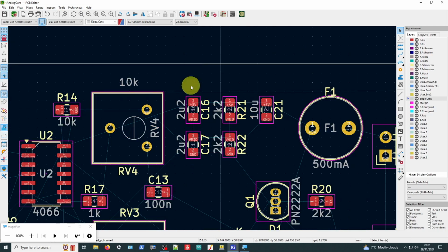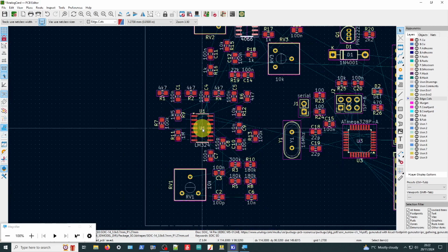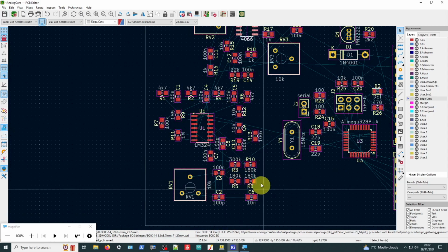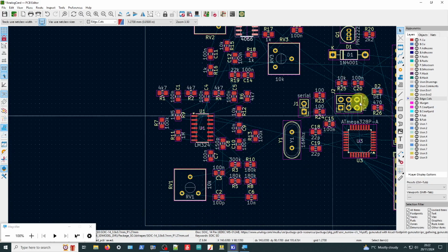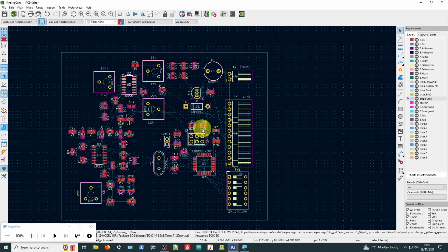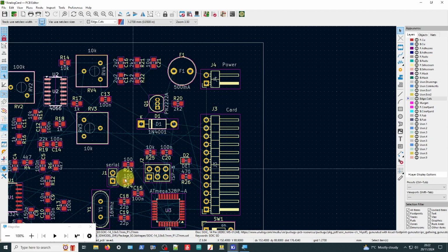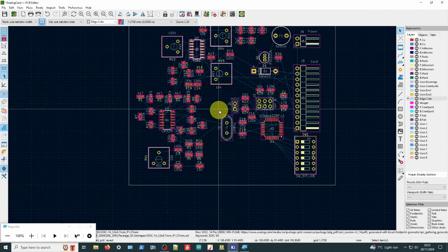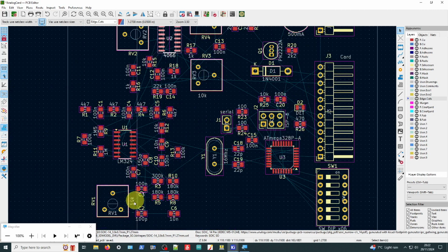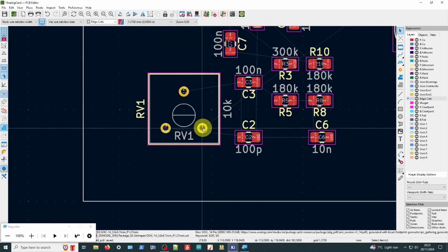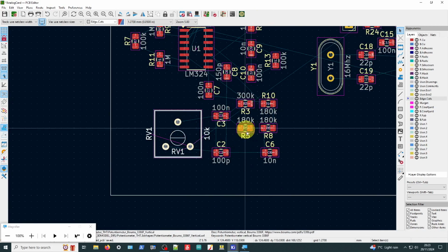This is our V-mid circuit here. This is going to create the V-mid from the positive rail, if you can visualize that. This is the LM324, and down here is basically the passive components for the low-pass filter. The signal from one of the connector pins comes in. It looks like it's this blue one coming right through here. Might be. Yeah, comes all the way through here and goes right to that connection just there. Passive components, which is part of the low-pass filter.